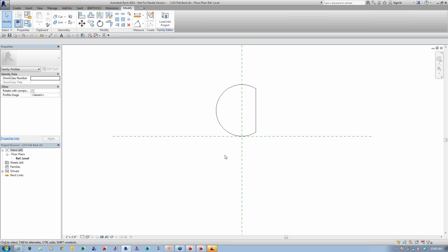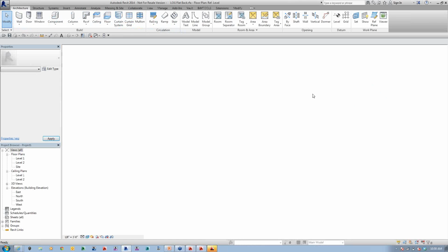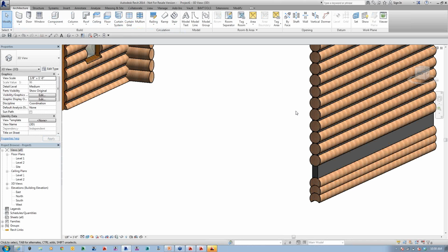Michael asks about being able to, on the overhang of the logs, you often see that kind of nice curve effect over the run of the logs as it goes up the wall, where at the end it has a nice curve. Yes, you could create a profile and cut that curve through, and then that's where it's going to be done. Okay, so Mike notes, yeah, for an 8-inch log, the stack height is 7 inches. Right. Okay, so on a 12-inch log, it's going to be 11 inches. Hopefully that will cover that.